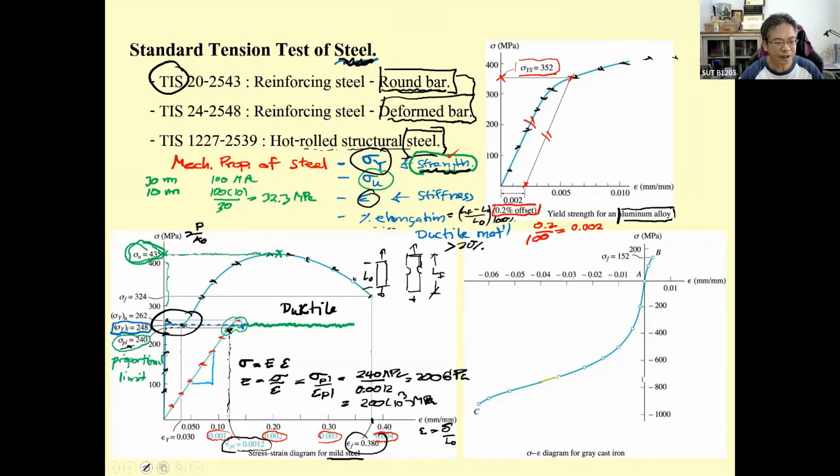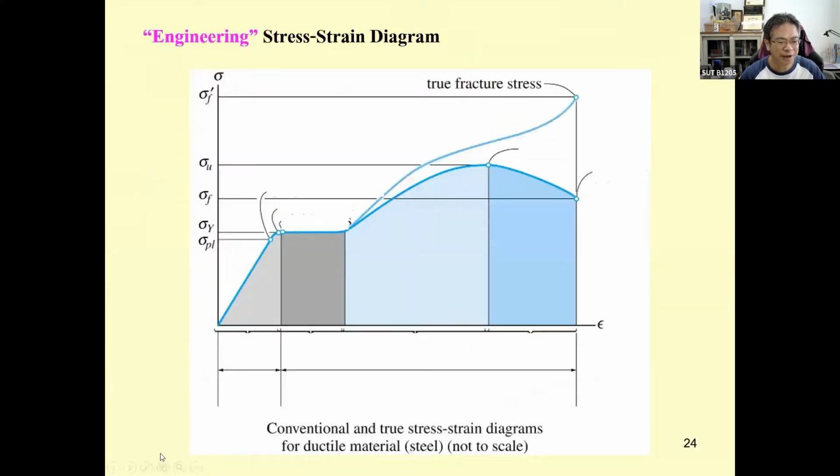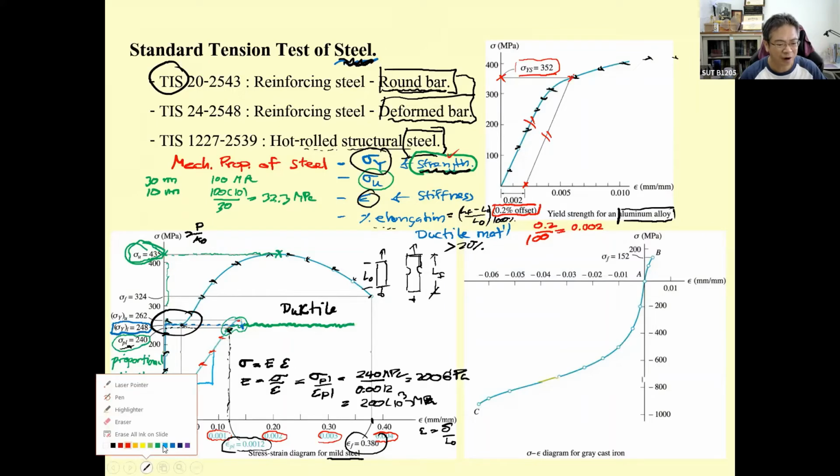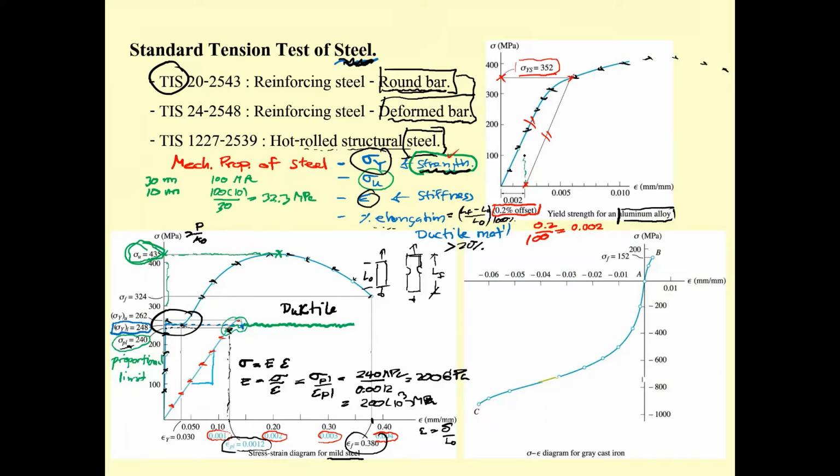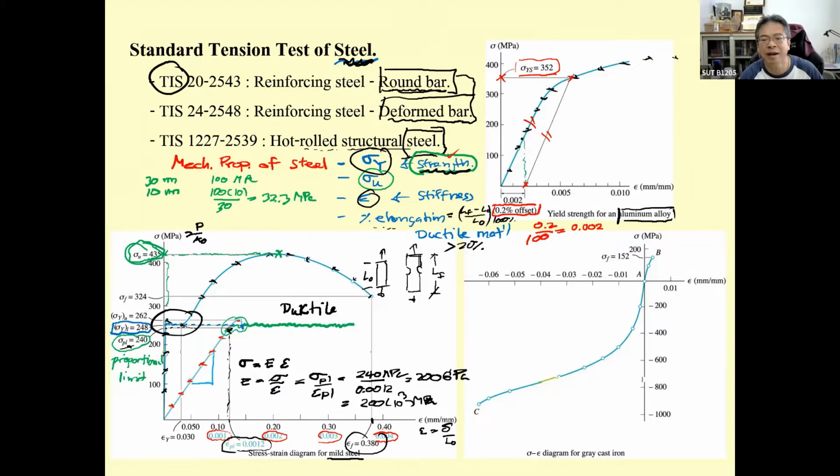And again, if you prefer to determine the slope of this one, you may pick one value such as this one, and then you take the vertical line and hit over here, and then you may project it over here. By doing this, let's say I got this one about nearly a half, and do the proportion as before, and let me assume you get this one for 150 megapascal.